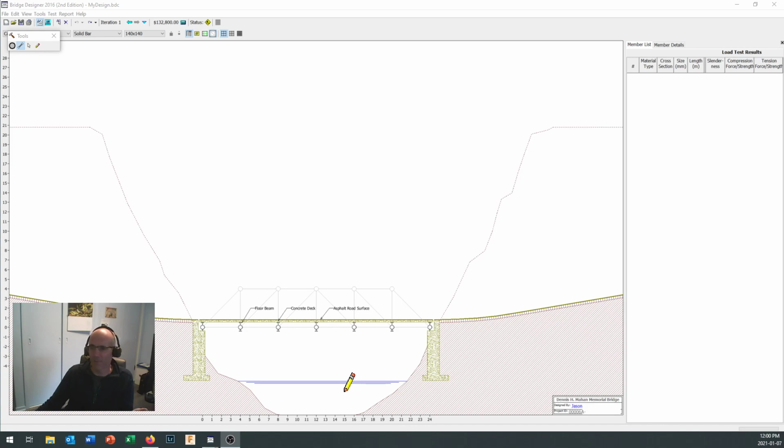Why don't they do that for every bridge? Well, obviously, you're going to run into environmental considerations. Removing all this dirt right in here is probably not keeping nature nice and pristine, so it may be better to run right across the top. The other thing is the slopes required to come down in here. The maximum gradients we like to have on slopes for vehicles are somewhere around 6 to 8%. Trains can only get by with 2 or 3% gradients.